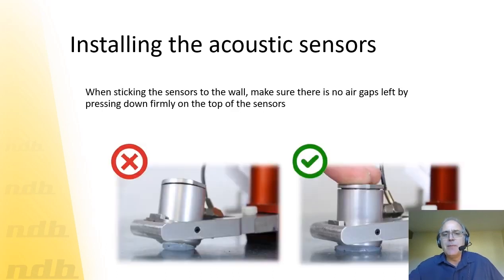And then make sure that your sensors are totally in contact with the structure. So you see, sometimes there is an angle, so make sure to push all 4 sensors around to make sure that you have good contact with the steel structure.